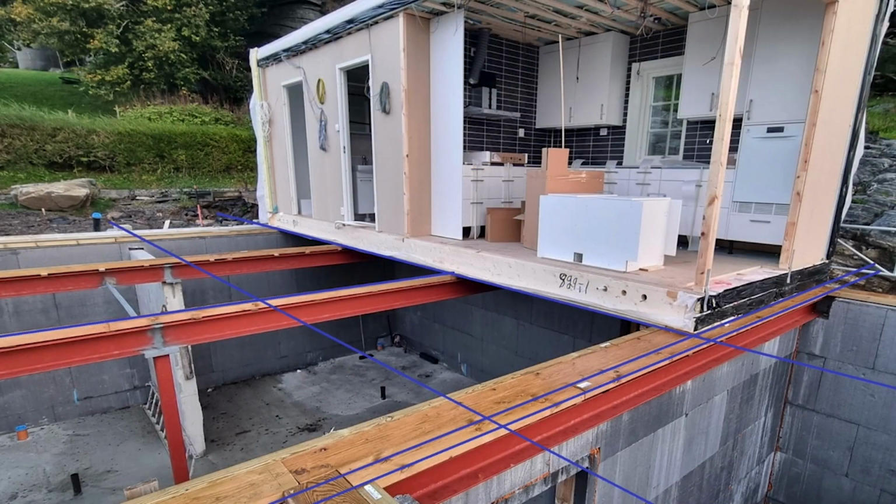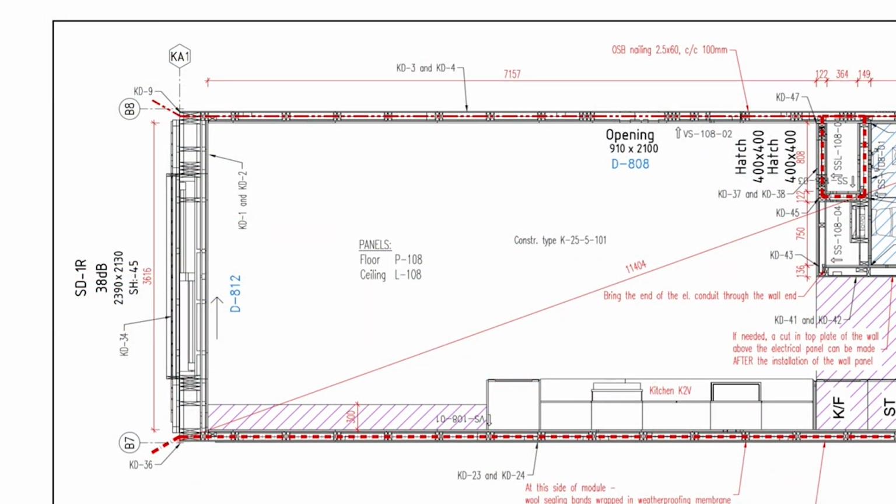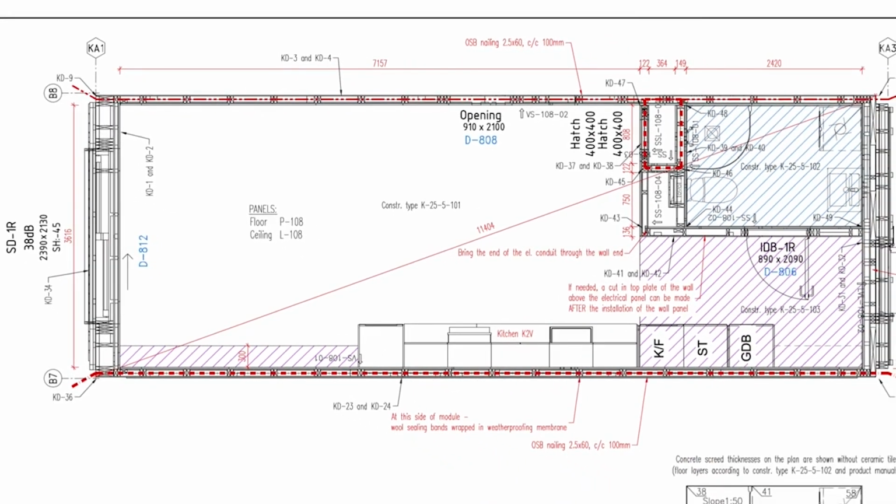The module as a whole consists of the floor, walls, and ceiling. Therefore, it is important to mark all related elements on the drawing. You see that floor and ceiling are not separately visible on the plan, but they are marked as text and symbols. This method simplifies the assembly drawing and avoids confusion, making it easier to focus on the details related to the assembly of elements. Since parts of the interior, like kitchen or bathroom furniture, may be installed in the module at the factory, these are also shown on the plan.